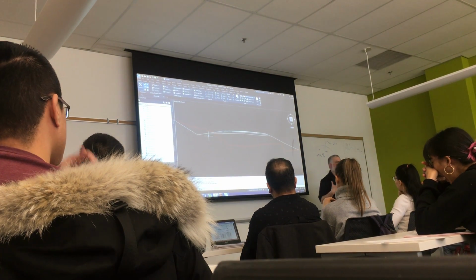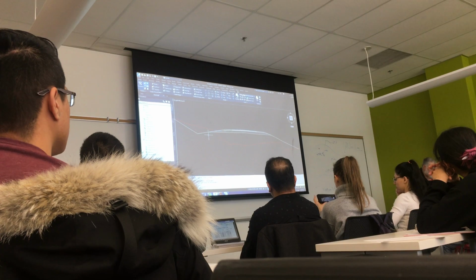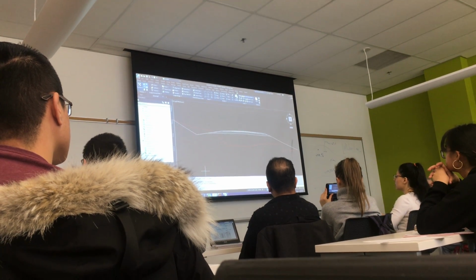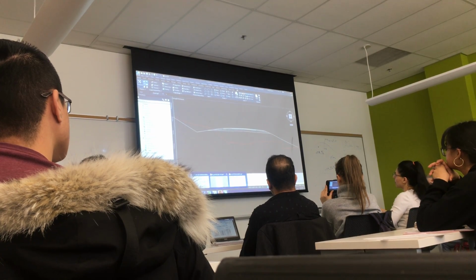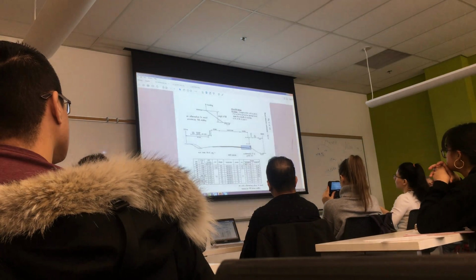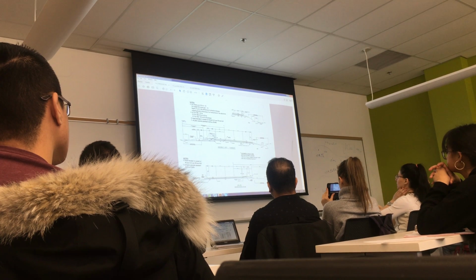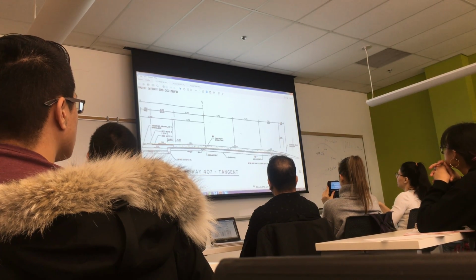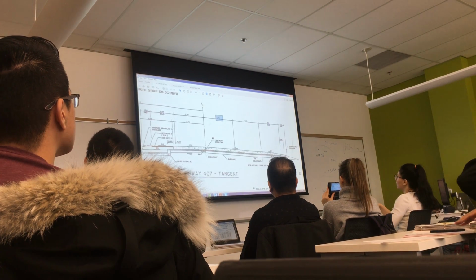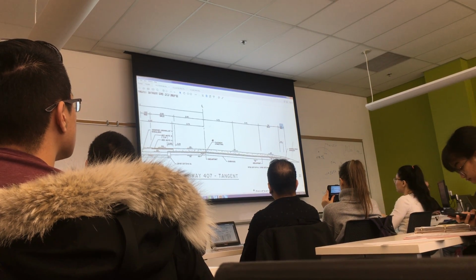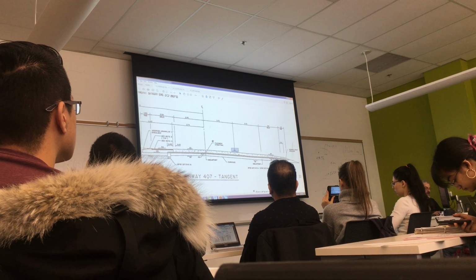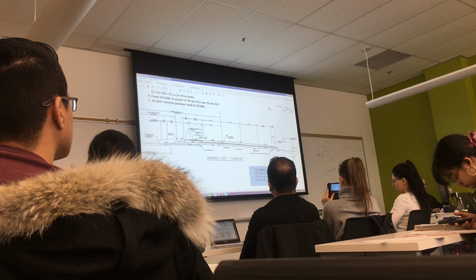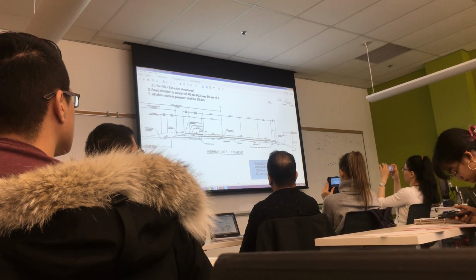Okay? And examples of what you're drawing are in the last few pages of the document. Let me show you. So you want to know kind of an example of what's in, what's out? Let's go back to this document. If you look at the last few pages of the entire document, you'll see typical sections with all the information, right? So if I had to draw this, there's the lane width, there's the shoulder width, there's the rounding, there's the crossfall in the shoulder, there's the crossfall for the lanes. How thick are the pavements? There's a note right here. I know the thickness of each layer.